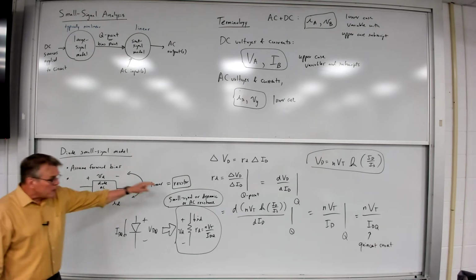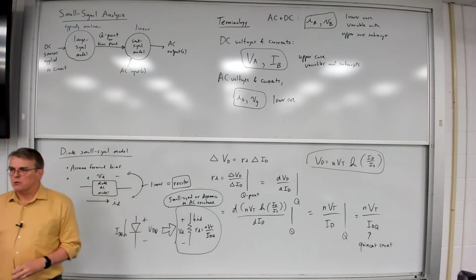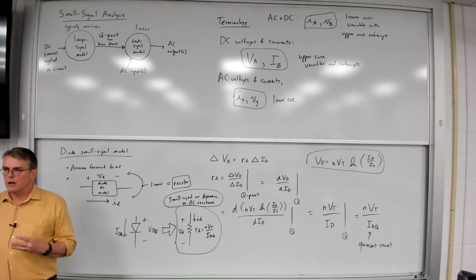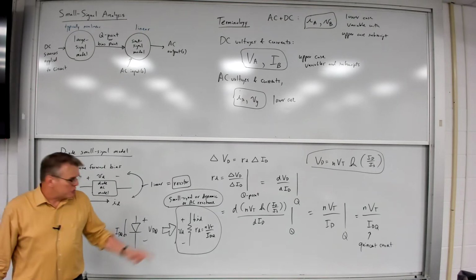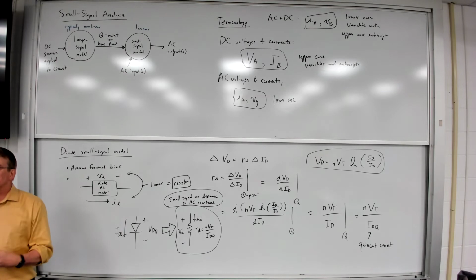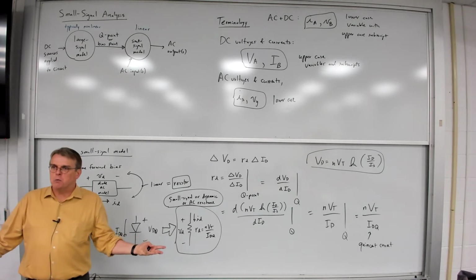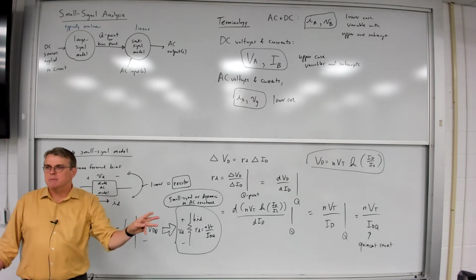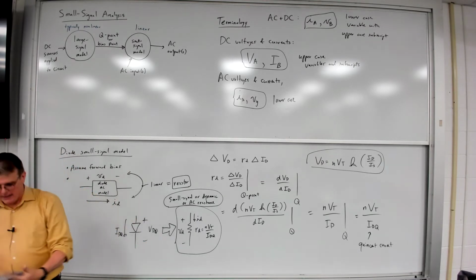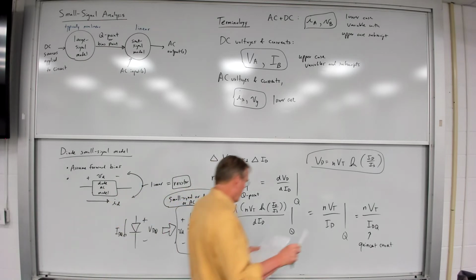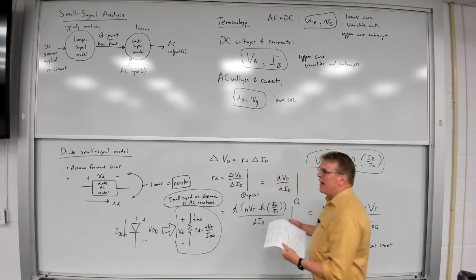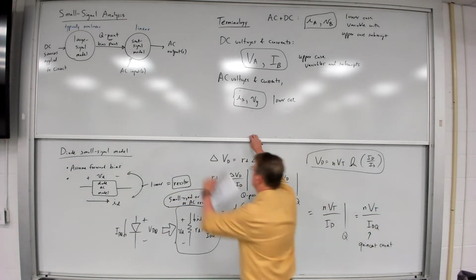All right, now if we're going to use this dynamic resistance for calculations, it's not enough just to transform the diode. I have to transform the other elements in the circuit as well, just as we did with phasors in Circuits 1. Every element in the circuit has to be transitioned over to the correct domain. So let's consider how we would transform other elements.